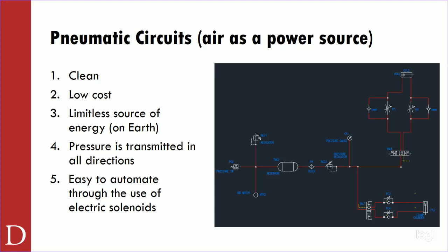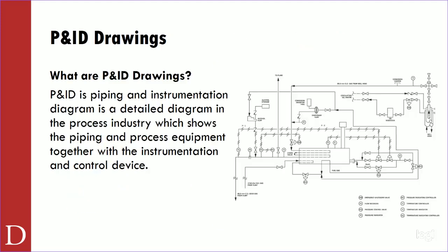So you'll see different symbols meaning different things. So tonight we'll start off with some pneumatic circuits. And first off, why do we use pneumatics? What are pneumatics? Everyone's sitting in front of a robot right now. What's on the end of that robot? Yeah, it's a pneumatic gripper, isn't it? Why do we use a pneumatic gripper on the end of that robot? It's cheap. That's exactly right. That cylinder that's actuating is fairly inexpensive.